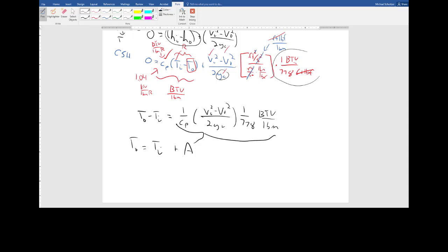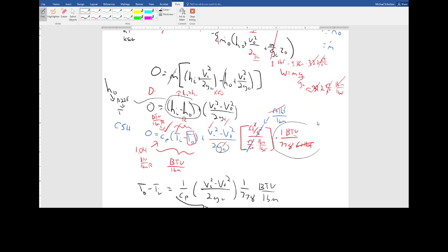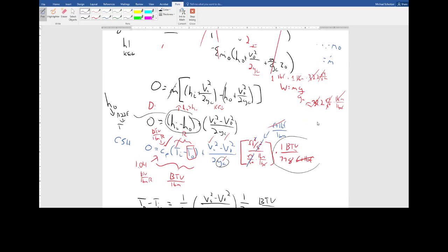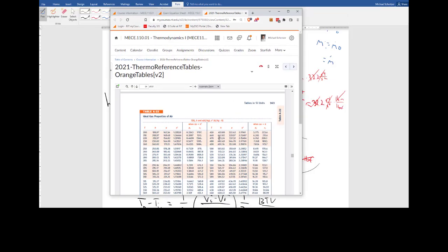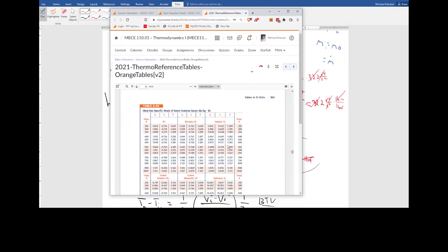Oh wait, can you scroll up a little bit? Did I forget a factor of 4 somewhere? It's saying nitrogen gas. I'm not sure that plays. Maybe we looked up the wrong value for CP. CP for nitrogen though, because air is mostly nitrogen, right? So it's still, and we looked it up at 290, right? You're not going to get a factor of 4 out of that, right? Like it's not even on the table.